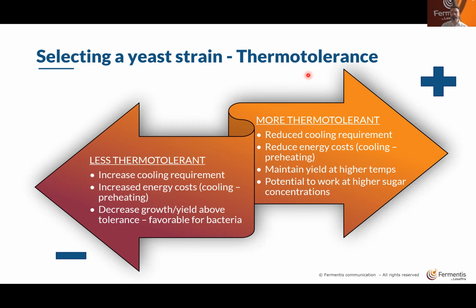We also have to take a look at the temperature. So we'll talk about thermotolerant yeast and less thermotolerant yeast. The advantage of thermotolerant is that you don't have to use, or you have reduced, cooling requirement, which can be a very good advantage. The fermentation will also be faster, with reduced cost. With less thermotolerant yeast, of course, in some cases you will have to cool down more, which will bring the cost up, but at the same time you will have other aromatic pathways that will be available. So it can also be interesting. But you have to know about this in order to choose the right yeast for your process.